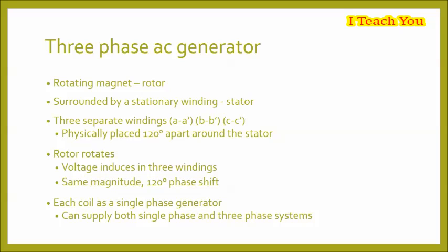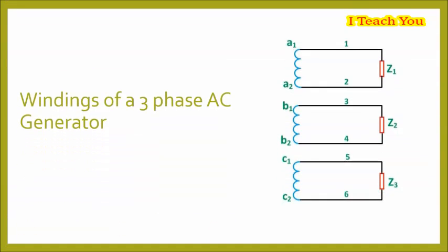In a three-phase AC generator, there are 3 windings. Each winding has 2 terminals, start and finish. If a separate load is connected across each phase winding as shown in the figure below, then each phase supplies an independent load through a pair of wires. Thus, 6 wires will be required to connect the load to a generator. This will make the whole system complicated and costly. Therefore, in order to reduce the number of line conductors, the three-phase windings of an AC generator are interconnected.